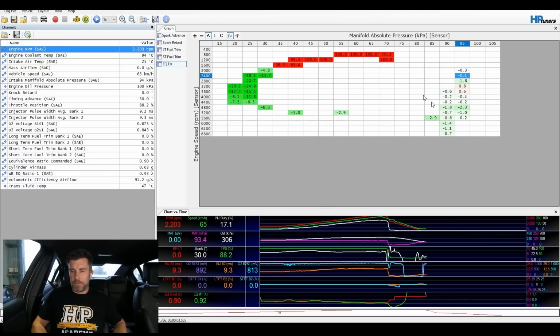These aren't really relevant here, but what we've got here is the data that we've captured during that wide open throttle ramp run. I will talk a little bit more about what these numbers mean and how we can generate these, but essentially this is how close we are to that target. You can see that for the most part we're pretty good there. Basically we're within 1 to 2% of our target the whole way through.